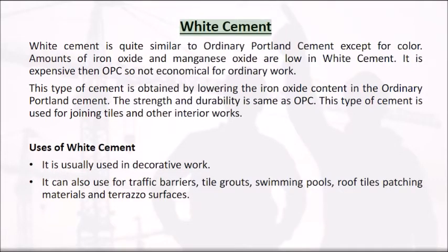White cement. White cement is quite similar to ordinary Portland cement except for color. Amounts of iron oxide and manganese oxide are low in white cement. It is more expensive than OPC, so not economical for ordinary work.